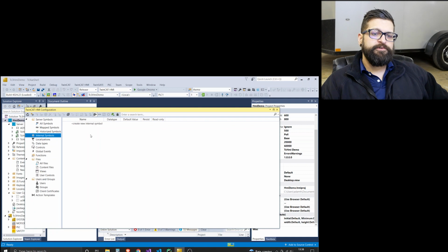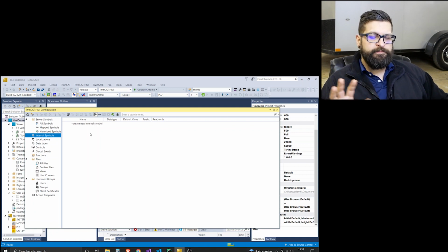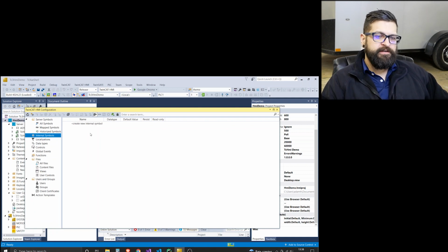Also, sometimes when you're moving objects out of view of the operator, I'll set up a constant integer that's a position for either left or top or bottom. That's a positioning, a layout property. So I'll just use that constant. So when I'm moving controls into the screen or hiding them from the screen by moving them out of the viewable space, it's always going to the same values, and I don't have to hard code an integer for that.